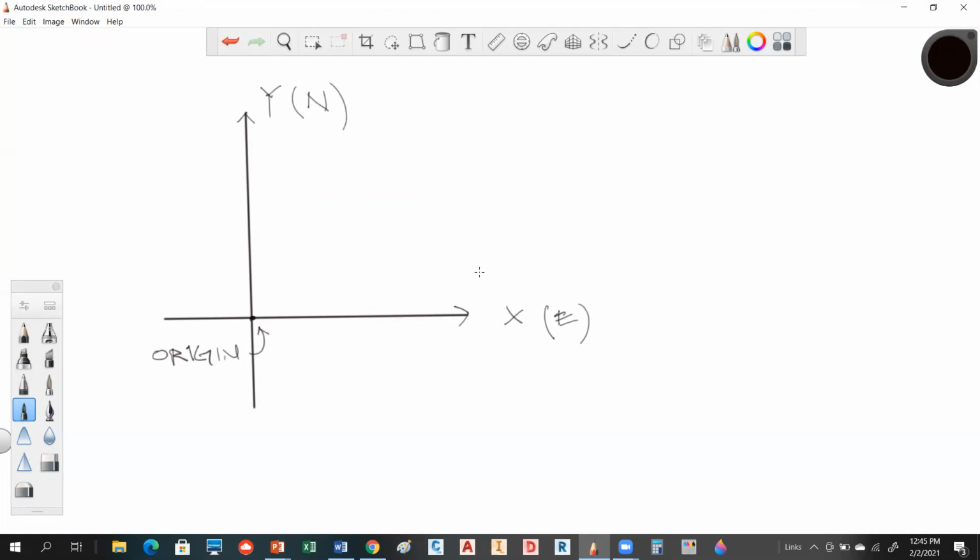When you have the right-hand rule, what you're saying is angles turning this way are going to be positive. Again, you're used to AutoCAD. AutoCAD uses the right-hand rule, as do a lot of things we deal with in math. Now, some of the things we talk about in surveying, that's not true, because when we turn an angle this way in surveying, we usually consider that a negative angle. This way is a positive. So there are subsets of that you've got to think about.